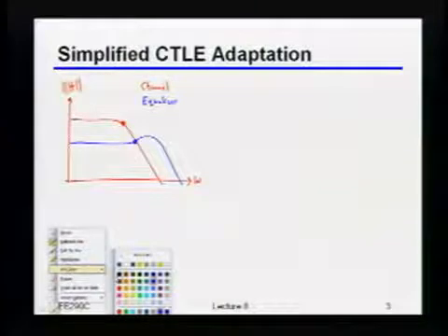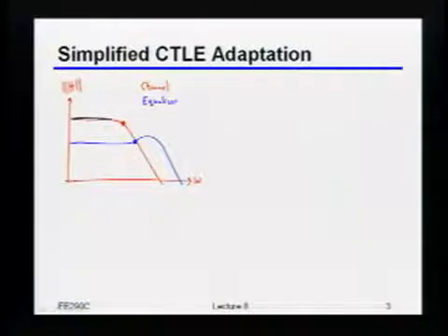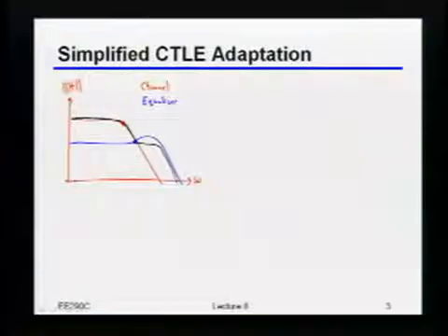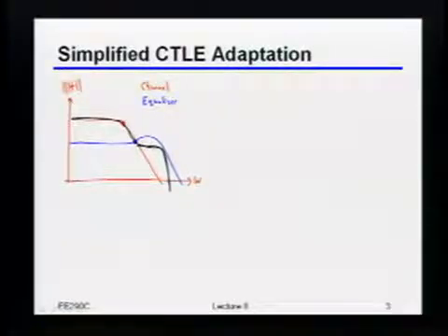Yeah, I think Chintan kind of did it. So basically, obviously down here it's flat. Then you hit the pole of the channel, then you hit the 0 of the equalizer, and then it's going to... Actually, it'll be even faster than that because there's actually two poles there. It'll look something like this. So in other words, you're not equalizing enough, right? Because clearly you've still got some low-pass characteristic in that channel.